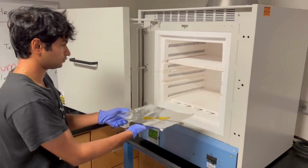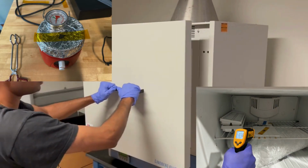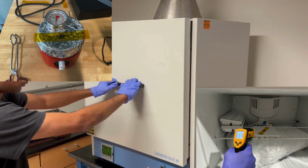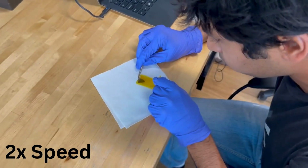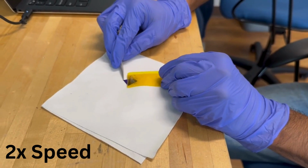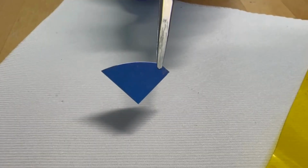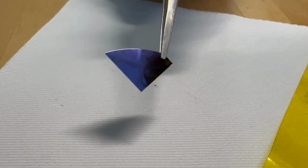Optionally, the tape and substrate can be temperature treated in an oven, hot plate, freezer, or other method at adjustable temperatures and times to promote adhesion and flake transfer. Once prepared, the tape is slowly peeled off of the substrate. After this step, it is important to keep the substrate clean and undamaged, as there are now thousands of flakes of varying size and shape on the substrate.